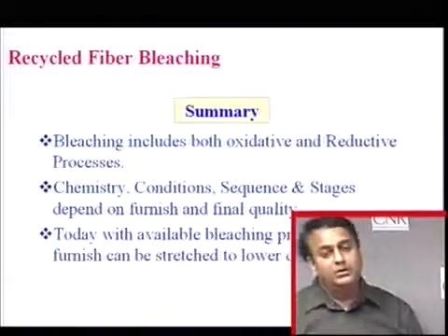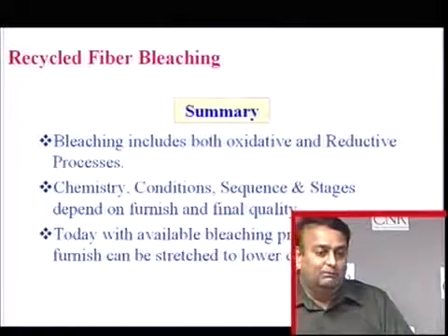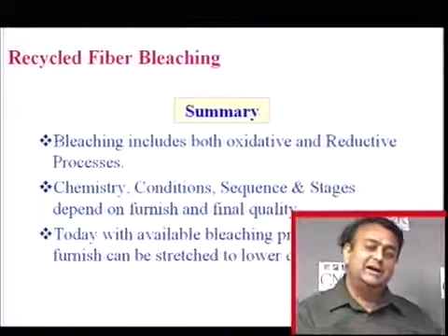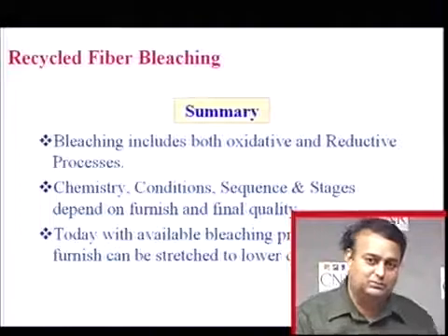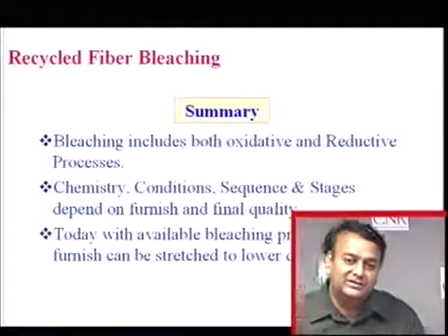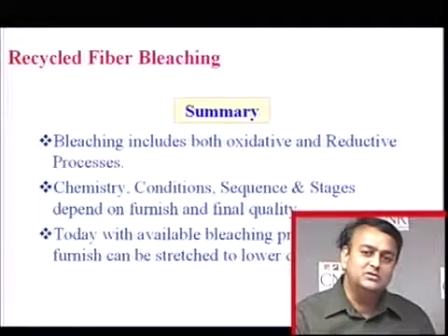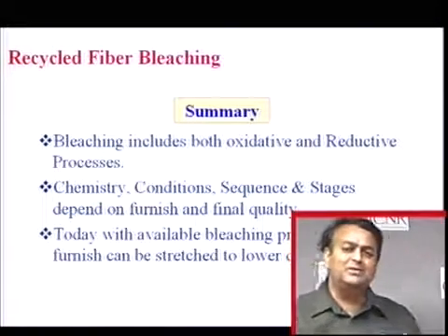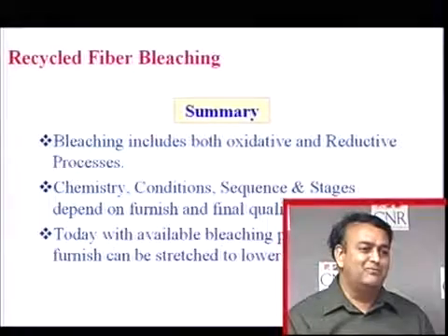In summary, recycled fiber bleaching is exciting because it contains chemical fiber, it contains mechanical fiber, it contains brown fiber, it contains once bleached fiber. That's why it's called recycled fiber. It also contains dyes, ink, fillers, fluorescent whitening agents. All these compounds present in your fiber can make your bleaching challenging.